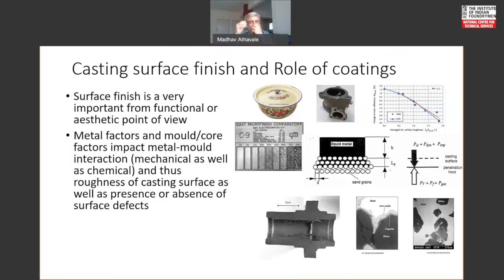Then as the sand surface layers get exposed to the heat of the metal, the top layer in immediate contact with the metal will initially expand as silica undergoes phase transformations. And beyond 573 degrees, it actually starts contracting. So the top layers will start contracting shortly after they cross that 573, 575 degrees, while the lower layers are expanding.